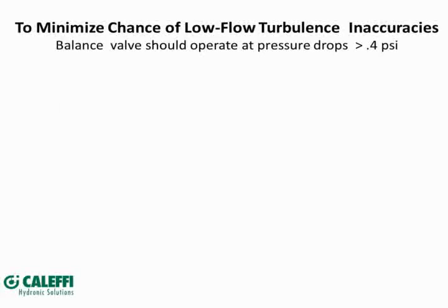Presetting is a way of predetermining the knob position for a balancing valve to give you the desired flow rate on that circuit, thereby making the balancing contractor's task a heck of a lot easier. So we'll talk about that too. So back to selecting a size.